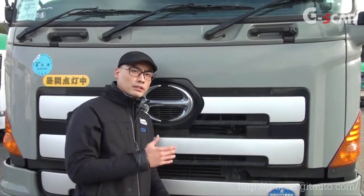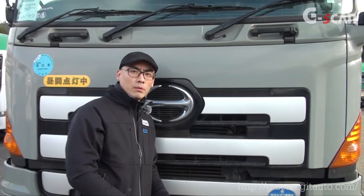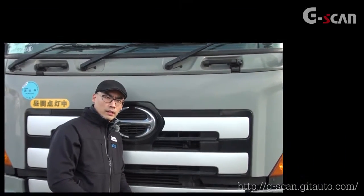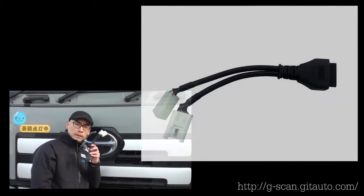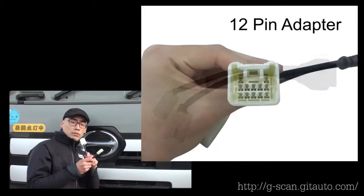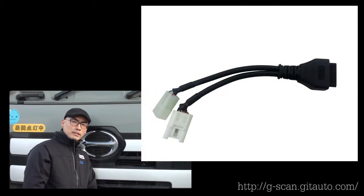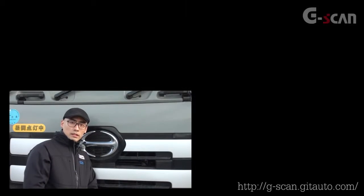We have found the DLC location. Now we need special adapters in order to communicate with Hino commercial truck. This adapter is specially designed for Hino commercial truck. It's got 12 pin and 5 pin in one adapter. This adapter does not come with standard kit, so please contact your local dealer if you would like to have one.